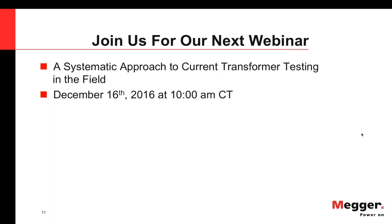So you might see a lower voltage as well when you hook up something like that. So you have to take into account that whenever you put any correction device on a system, you have to look at everything on that system to make sure that you didn't correct one thing and cause another problem. So yes, they will reduce transients, but you just want to be sure you're not lowering the voltage as well. That could create problems.